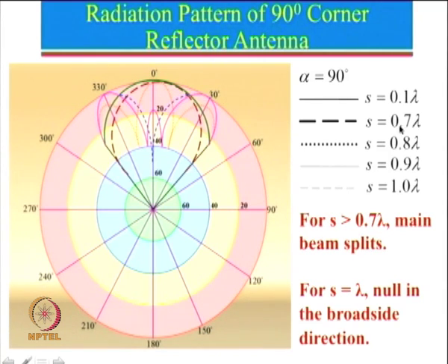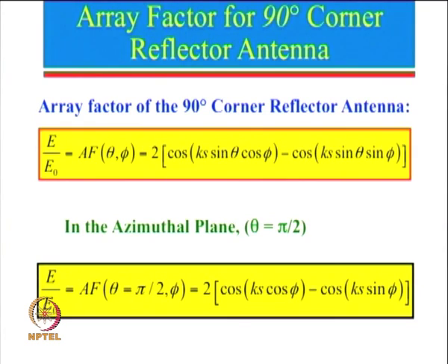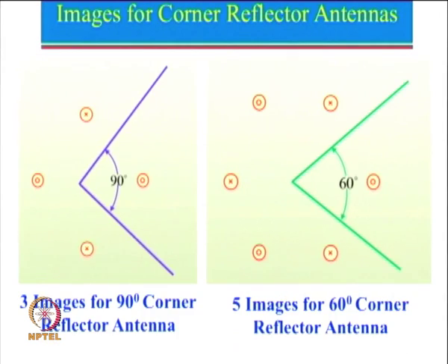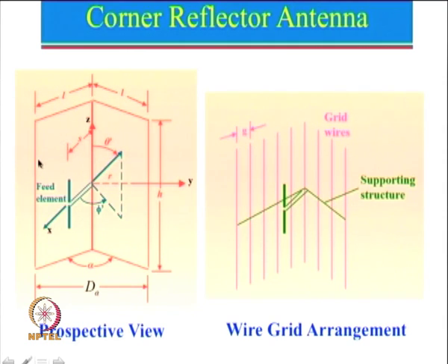Why do I say that? The reason is that all of these things assume that there is an infinite ground plane, but in reality there will never be an infinite ground plane. We are always going to take a finite ground plane. Let us look at the 3D view over here. In the derivation it has been assumed that L should be infinity and this H should be infinity. Practically we cannot do that. So, let me give you some practical cases here. We know that a dipole antenna will have, let us say, a length of lambda by 2.